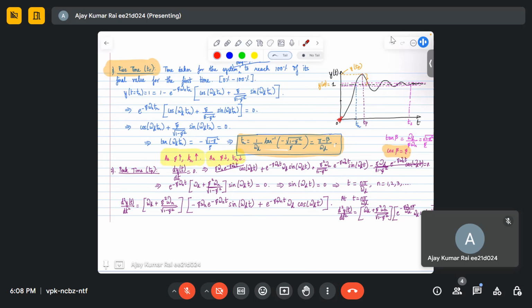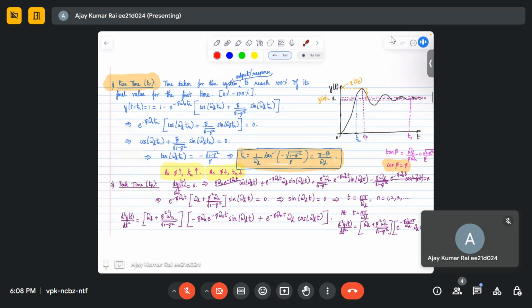Okay, for a particular damping ratio, this is the response that is shown here. So this is the response. If you increase the damping, again what will happen? Your response will become sluggish like this. And if I further increase the damping, how will the response be? Your oscillations will decrease, but your rise time will increase, right? Because it is going to the value of the input, that is 1, so it is taking longer to get to that value.